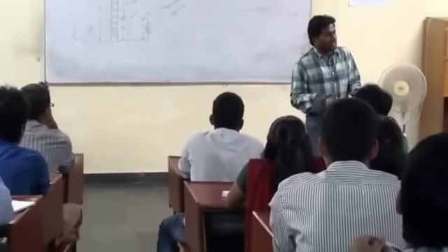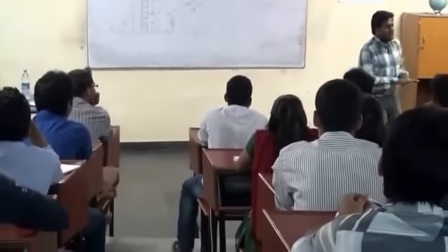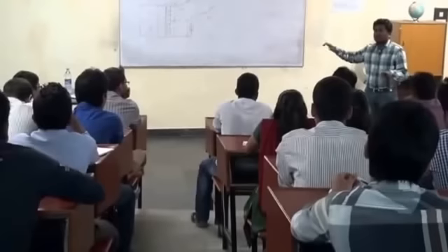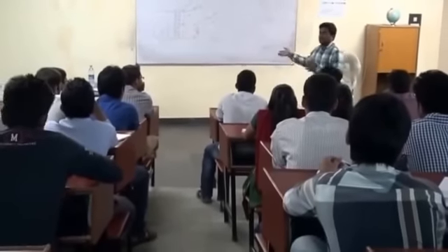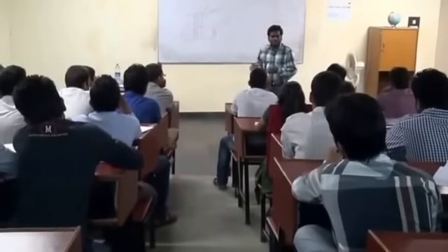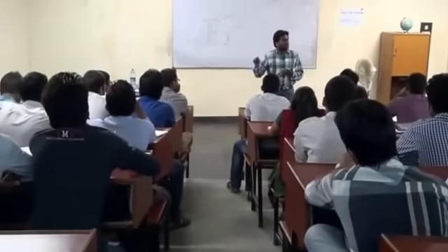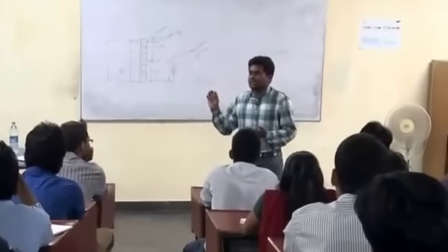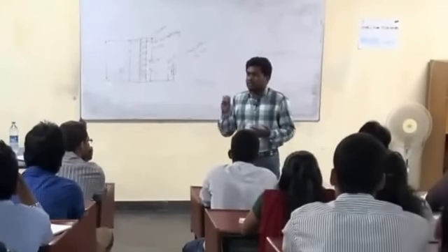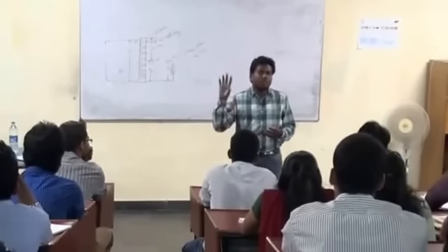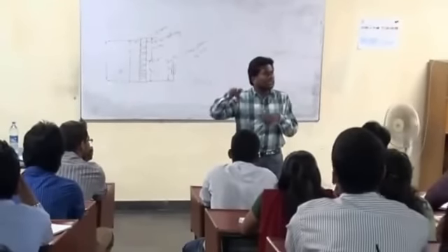Okay, the principle of operation of the transformer and of this auto transformer are both the same. Both act on Faraday's law of electromagnetic induction, that is E equals N d phi by dt. The only reason is that it will be useful where we require variation of voltage, variation ranges of voltage.